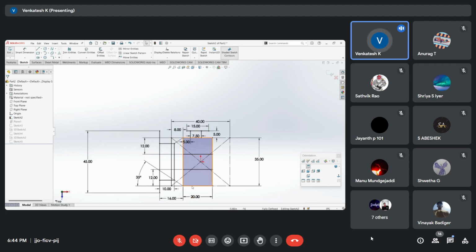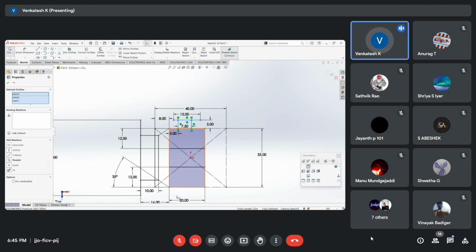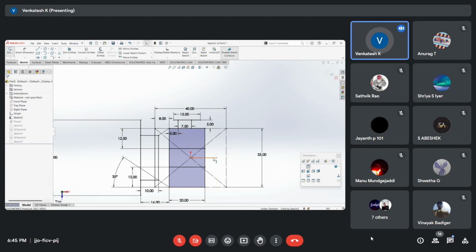We want this to be on the other side also. So we'll just select these parts, whatever we want to be mirrored. We can just mirror this on the other side so that we don't need to draw it again. Before we mirror it, we'll draw a line from the origin about which we want to mirror. This will be our reference line for the mirroring.